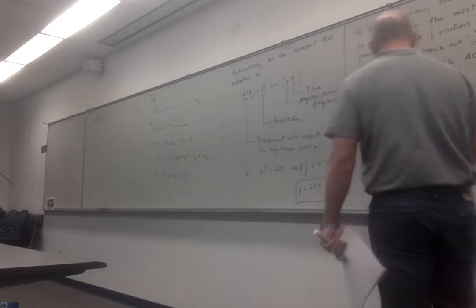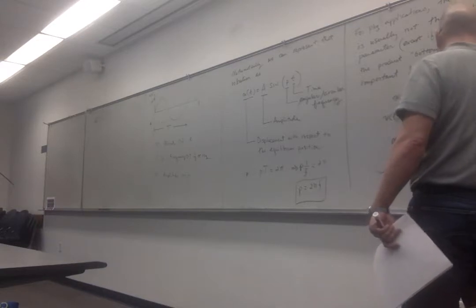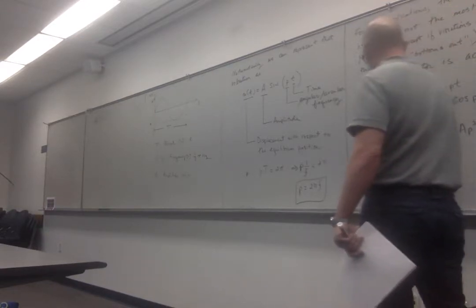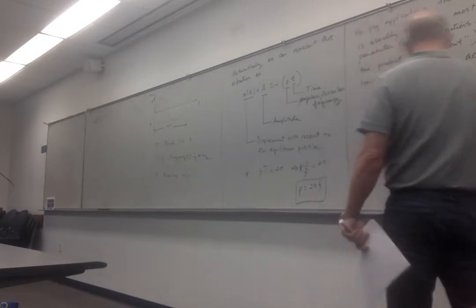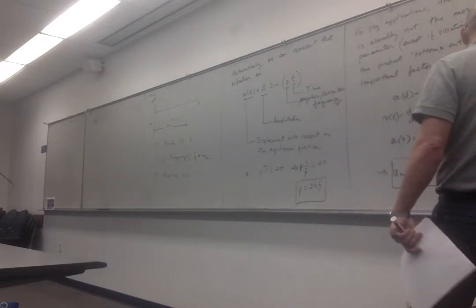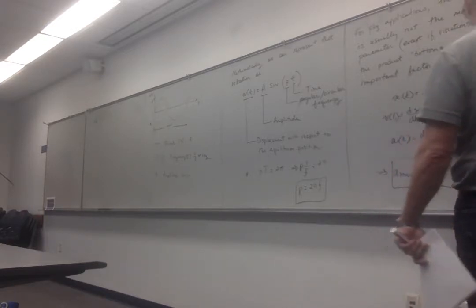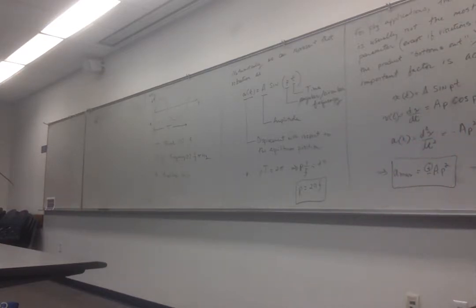Typically, we just use the positive value and circle that, but that will be very important. That means that typically when we ask for acceleration, we assume we want to find the maximum acceleration, and it's therefore equal to A times 2 pi f squared as well.